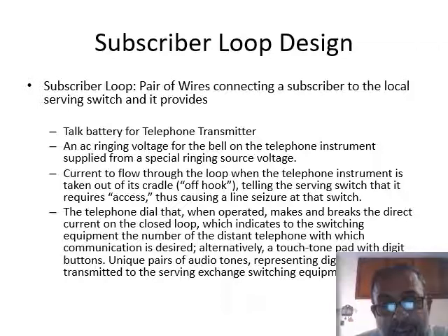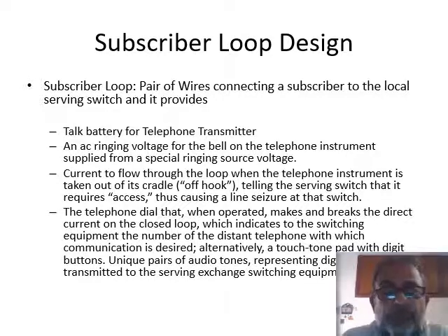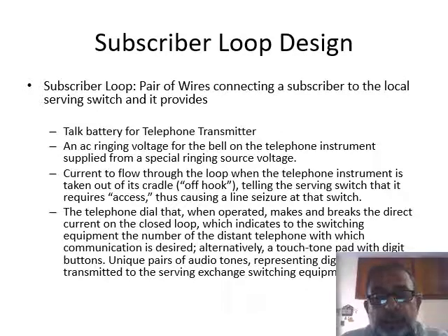On the vertical side, primary cables are connected or terminated, and these primary cables are normally of 300, 600, 900, or even 1200 pairs. And these large cables go out into the main roads and streets and go to a cabinet or the curb that is installed, which looks like an almirah, and it is installed somewhere around the corner of your street.